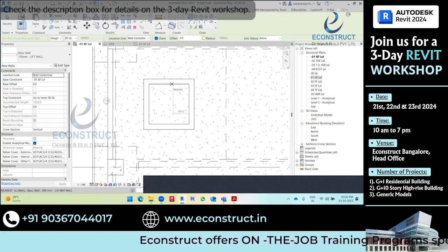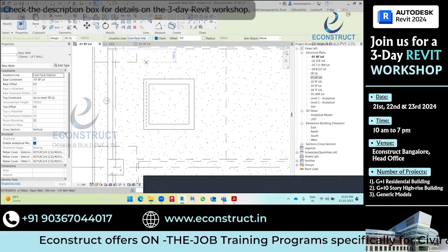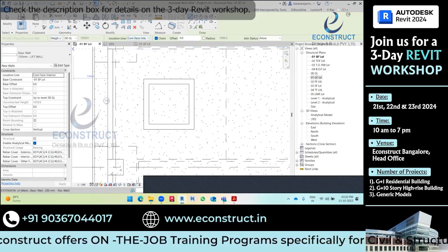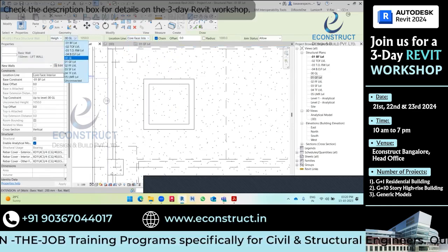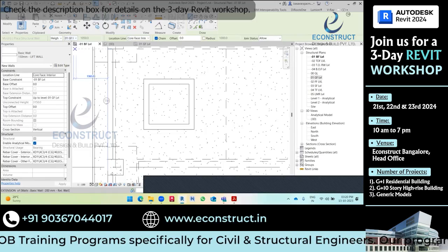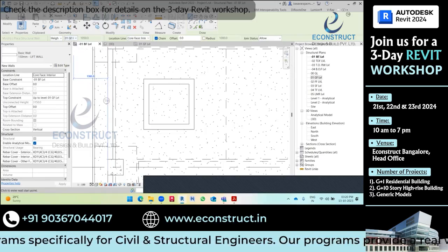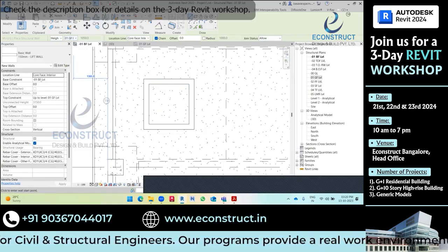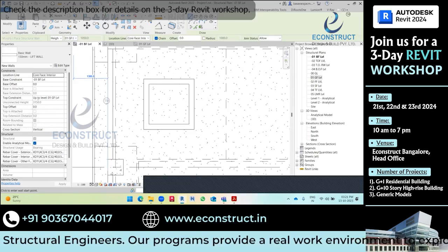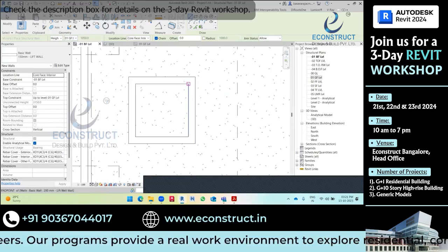Now the internal face should be flushed. The flushing should be on the internal side, so I will take core face interior. I have taken the height, and this wall should go up to ground floor level. So top constraint is ground floor level. Bottom constraint is basement floor level, as we are in the basement floor level now. So I will just draw the wall.